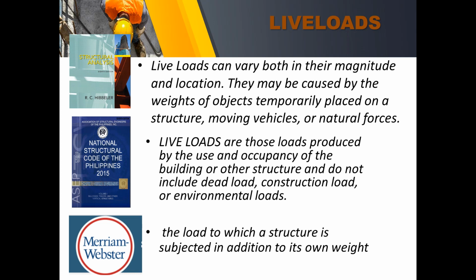So it depends actually on the occupancy. Live loads are those loads produced by the use and occupancy of the building or other structure that do not include dead load, construction load, or environmental loads, the load to which a structure is subjected in addition to its own weight.